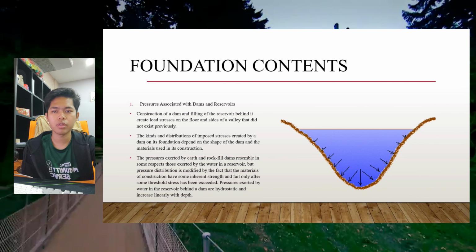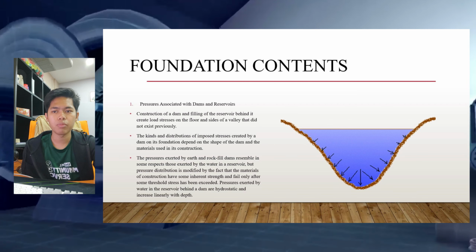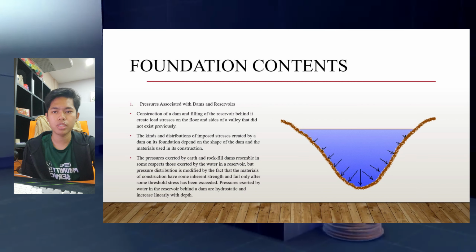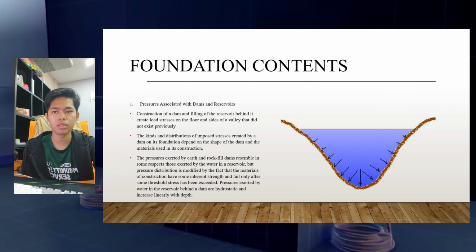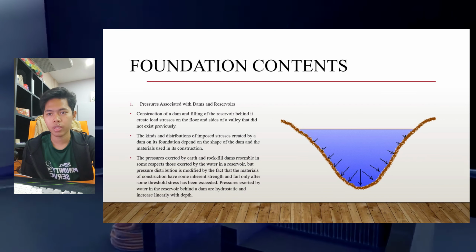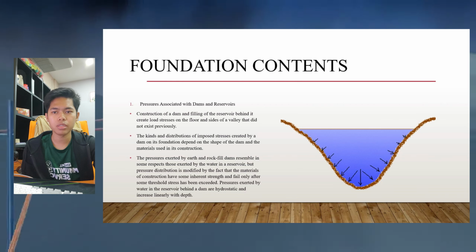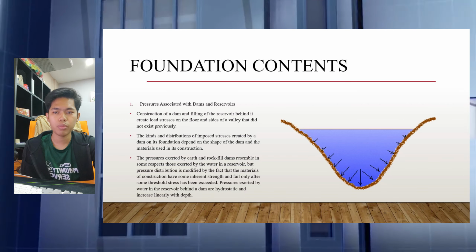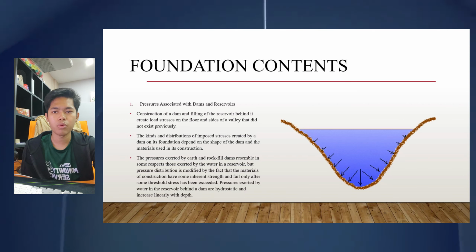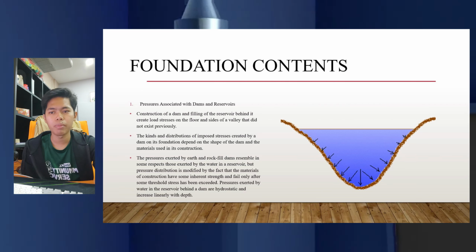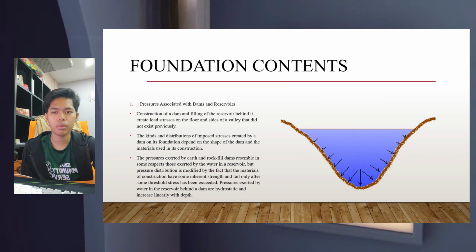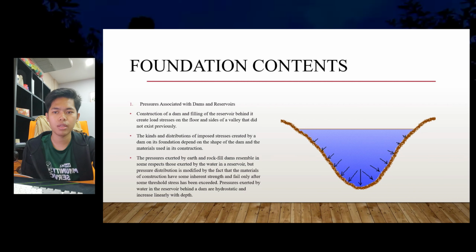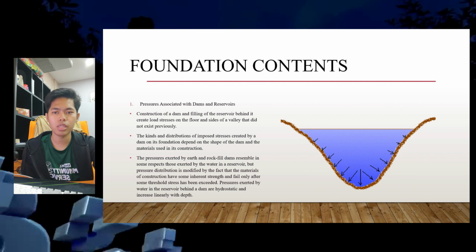The kind and distribution of imposed stress created by a dam fundamentally depend on the shape of the dam and the material used in the construction. The pressure exerted by earth and rockfill dams resembles in some respects that exerted by water in reservoirs, but the pressure distribution is modified by the fact that the materials of construction have some inherent strength and fail only after some